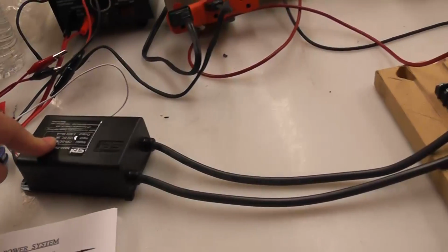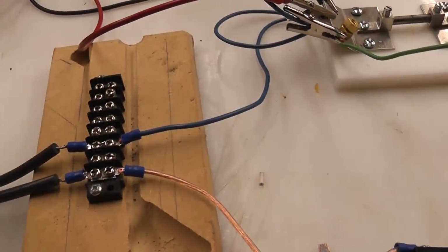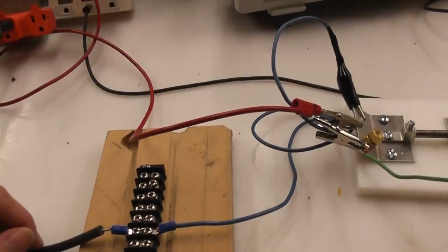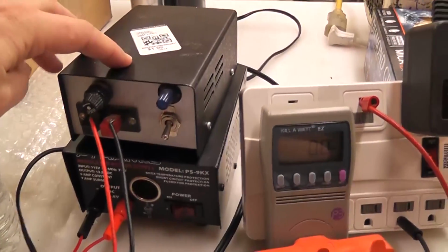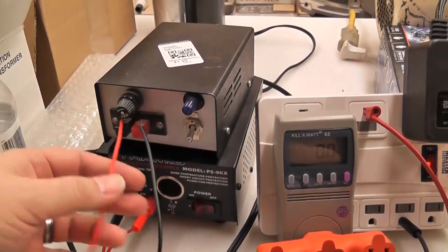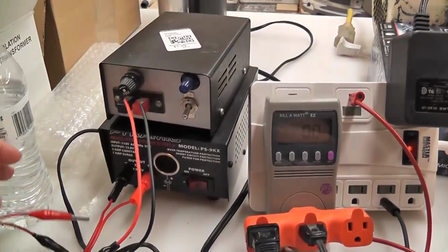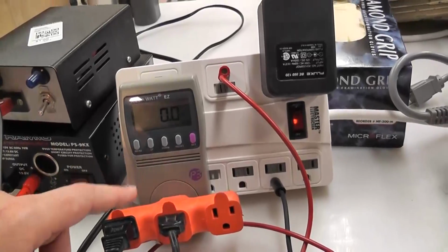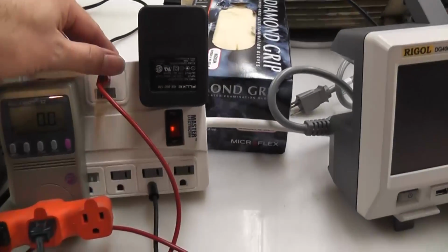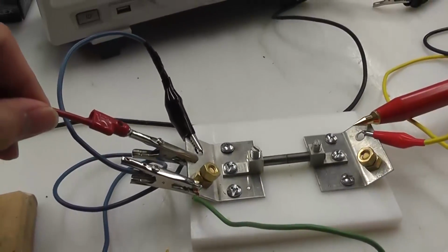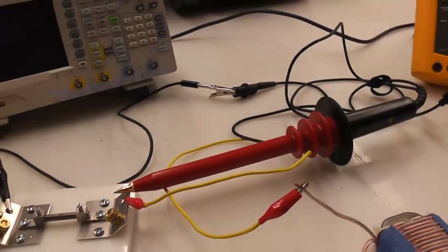Okay, so now what I have here is your neon sign transformer. I've got it pegged at this junction block here, so I don't have to hold any of the wires. I do have a watt meter, which both these power supplies are plugged into, but I'm only using the top one for this NST. And I've got the bottom one for something else I'm going to show you as well. I do have earth ground on here, so you can see what happens, and that goes from there to there. And I also have another earth ground which goes to my meter. The high voltage probe requires an earth ground.